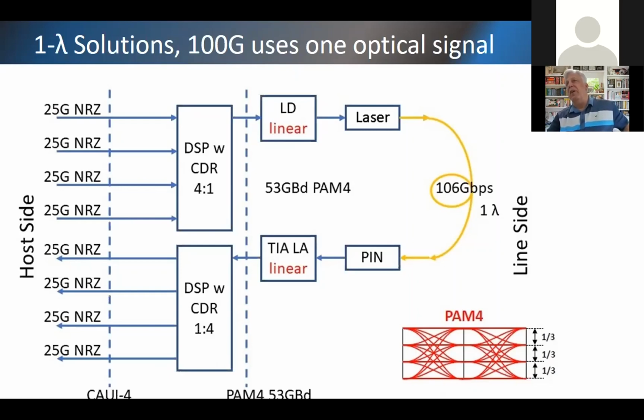If you can imagine, each one of these 100 gig transceivers is going to plug into one of the four parallel lanes of the 400 gig transceiver, which is also PAM4. So we have a PAM4 commonality on the optical side, as well as a robust KP4 FEC, which are going to let them interoperate together in a breakout application. So let's take a look at that visually.